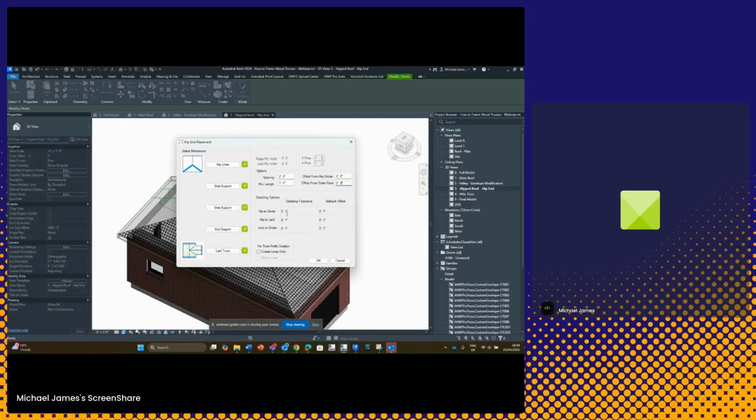So it's 2 inches. I need to take into consideration half of that member thickness, because when we generate our truss envelopes, the thickness of the member is being offset equally from the center line that we see. So that model line that's generated, the thickness of the member is going to be placed either side. So it's going to be centralized. That line will be centralized on our member thickness. So I want to leave a 1 inch offset.